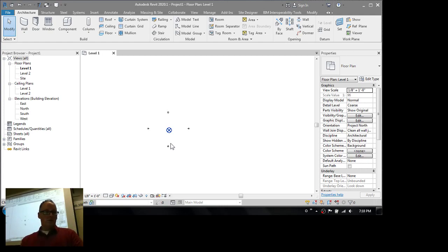Now, for those of you who have worked on big AutoCAD drawings, you've probably used 0,0 in AutoCAD as a point of reference so that when you're using external references from your consultants, you can bring them all in and have a common origin for those XREFs so that they all land in the same place. That way the structural engineer's drawings lay right on top of the survey drawings, on top of the mechanical engineer's drawings, right? You just import it at 0,0, boom, you're done.